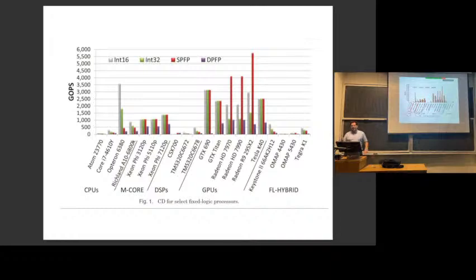So they use that AVX-512, really wide SIMD, simpler cores, more of them. It's intended to be an x86 processor targeted at essentially throughput computing. Like, give me more cores that are a bit slower to compete with GPUs and supercomputers. Probably not the processor you want to put in your laptop, but that's its target.